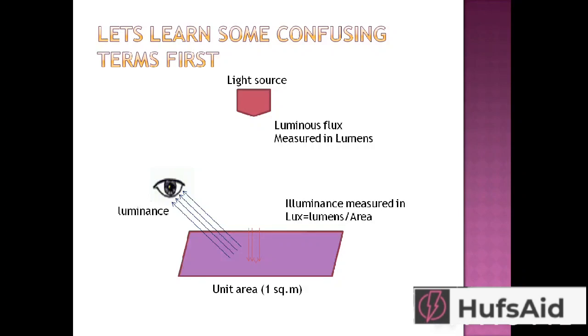While doing lighting design, I will have to maintain the lighting power density and lux level at a standard level. I need to meet a certain lux level and lighting power density. Now the question arises, how do I calculate lux? For calculating lux, I will make calculation surfaces at the height of our working plane, which is usually 3 feet.